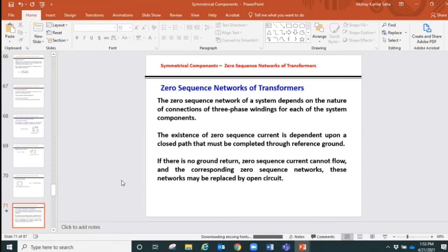We check the voltage because we want to see if the transformer is operating. If we apply this much voltage at the primary winding, how many volts are we supposed to get at the secondary side? Meaning the secondary is left open because we have not connected that isolator yet, or a switch, whatever it is. So the secondary can be left open in any condition if we need to, but we don't switch off unnecessarily unless we have to, like for load shedding.